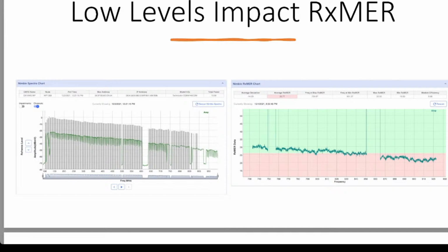What's interesting, and you and I know this, is that RF levels and RF noise get affected the same through attenuation. That's how we keep the same carrier to noise across the spectrum, because as the levels get tilted, the noise also tilts. So this is interesting because you're so far into the noise floor of the end device, the modem itself, that the MER is dropping. Normally if you had tilt going into a house but the levels were good, your MER wouldn't tilt also. But because you're so low into the noise floor, probably of the modem itself, that lower level and tilt is also equating to lower MER.